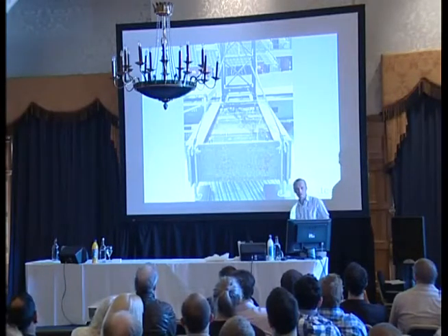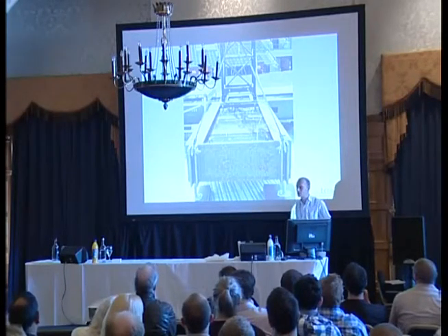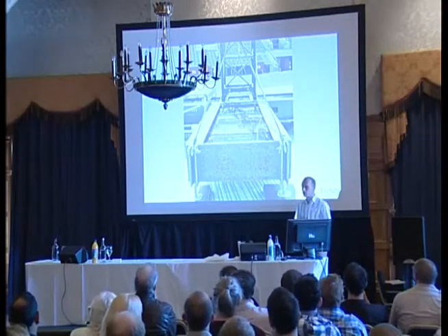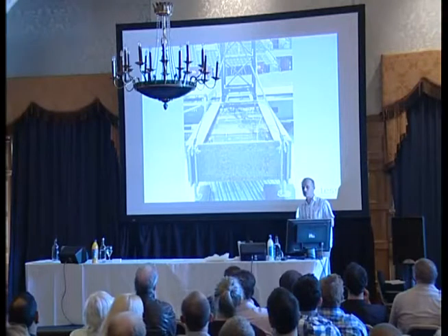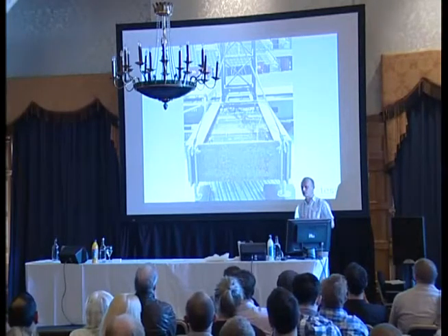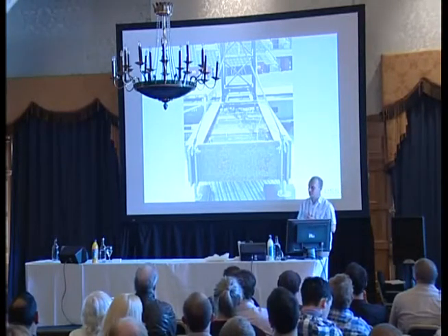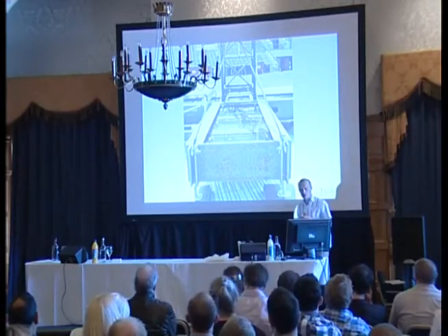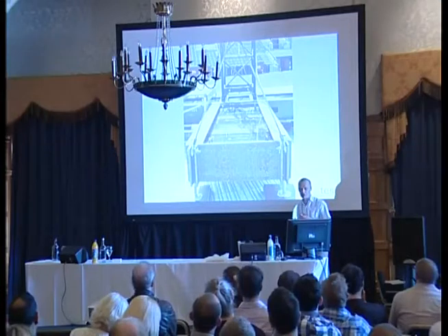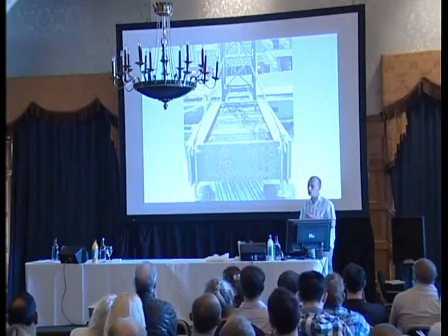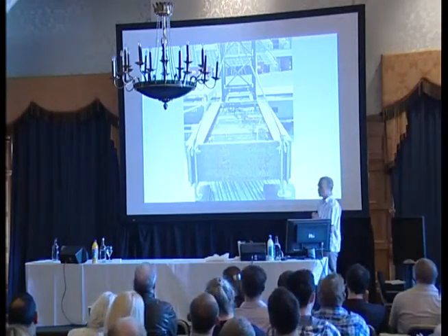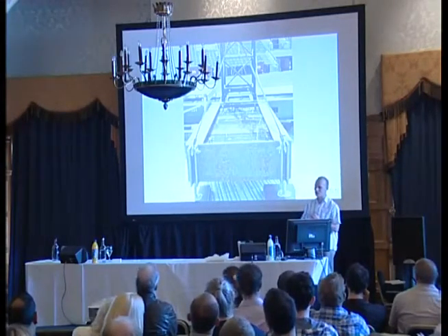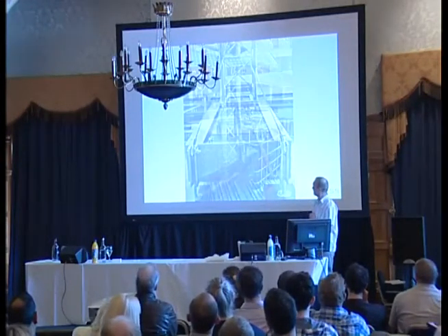It can leak. Evaporation, absolutely. Stick it out there in very hot weather, leave it there for a week, and your water's going to start disappearing. Your tower's still there with all the weight on the top of it. So make sure, as part of your testing or inspection regime, that somebody's checking that the water's in there all the time. Plus, if it's there long enough, there are all kinds of environmental hazards, but I'm not going to go into those at the moment.